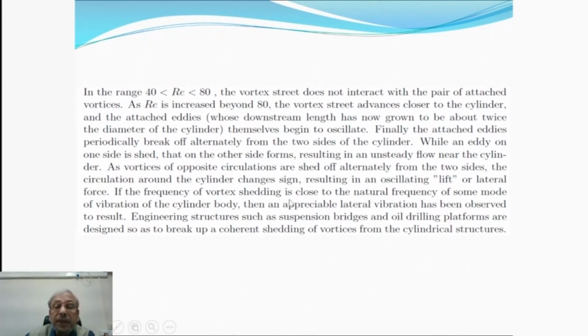If the frequency of vortex shedding is close to the natural frequency of some mode of vibration of the cylinder body, then an appreciable lateral vibration has been observed to result. Engineering structures such as suspension bridges and oil drilling platforms are designed so as to break up a coherent shedding of vortices from the cylindrical structure. The same is observed in bridge piers also.